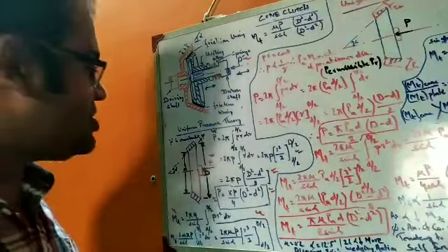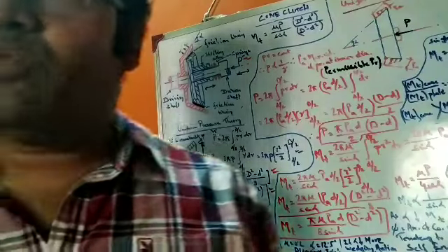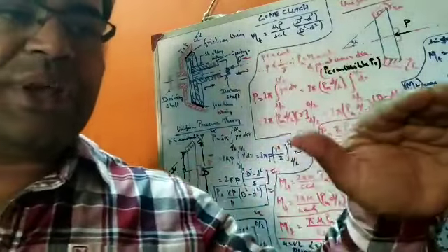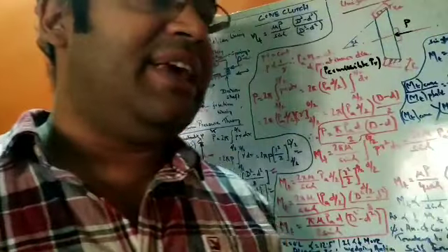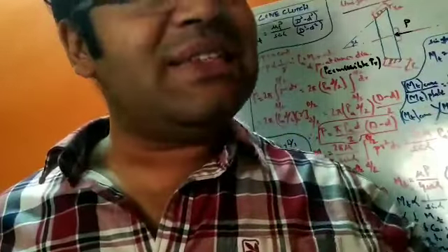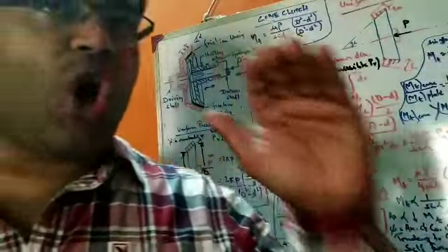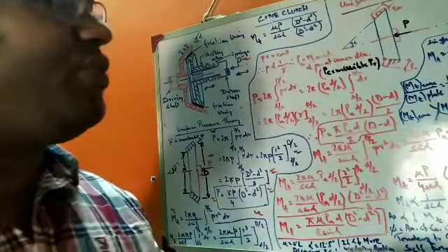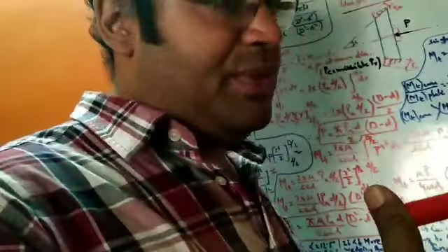First, for the uniform pressure theory we have seen what the constants are. Now we are going for the uniform wear theory. When you go to the uniform wear theory, it indicates that the pressure is not distributed uniformly. This happens because every time the clutch is engaged and disengaged, the friction lining may become worn out, and the pressure will not remain the same throughout. That is the reason uniform pressure cannot be held for a worn out clutch, so we have to go for uniform wear. We are thinking that the wear should be uniform.